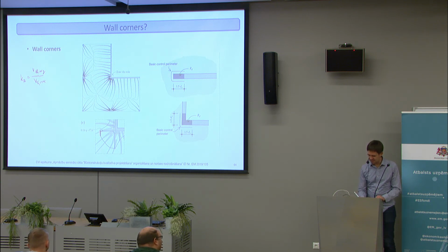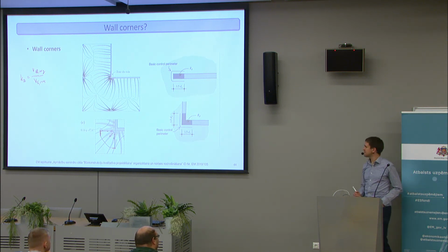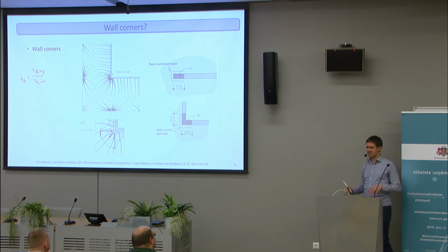In that case, you would have very high shear forces in the corners of walls. And in Switzerland, they do put shear reinforcement in places like this. They put a lot of shear reinforcement in, and sometimes it's not even possible to put enough shear reinforcement in such corners because you reach the crushing criterion between the first start and the column.